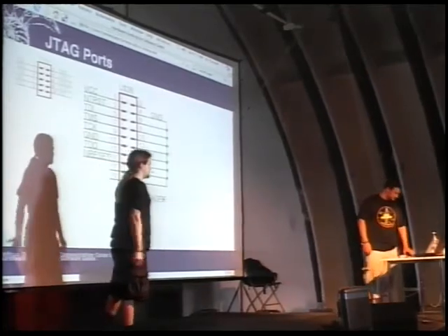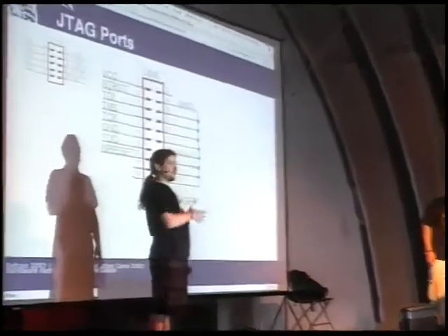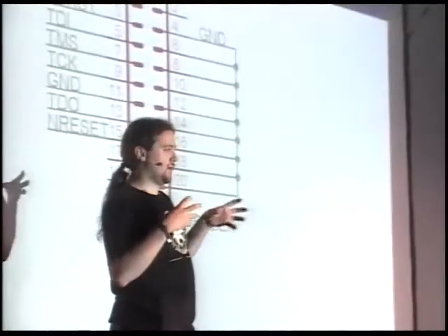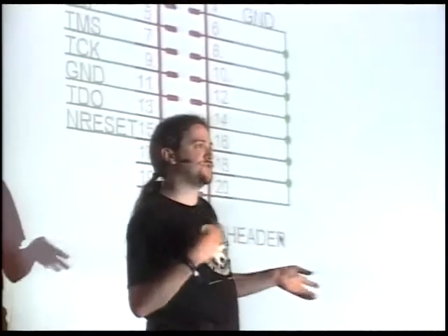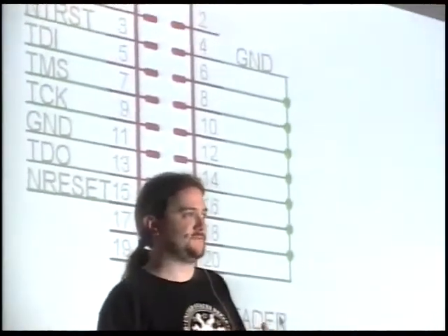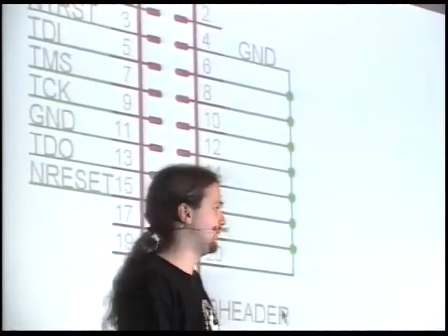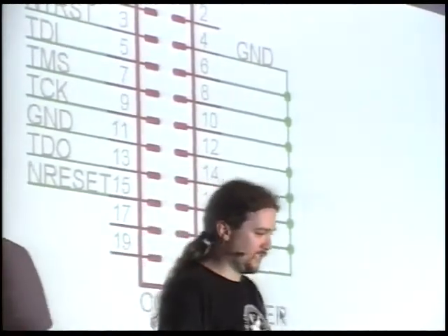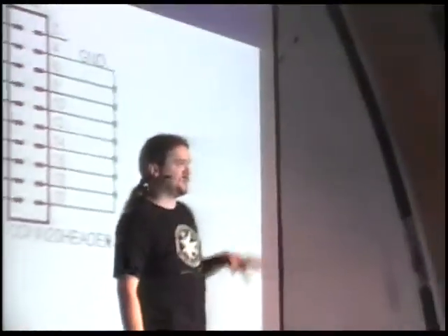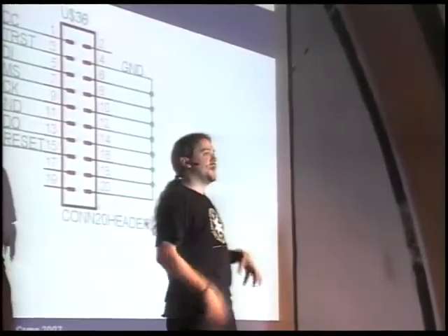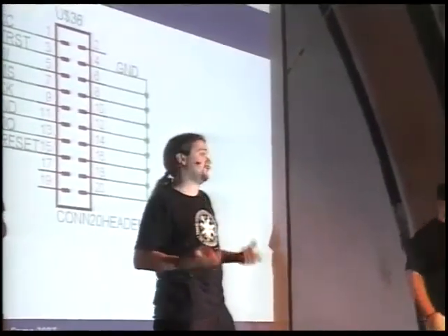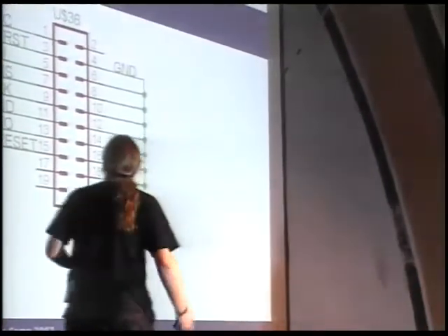Don't skip yet. While they're not standardized terribly well between manufacturers, usually one manufacturer will use the same JTAG pinout on all their boards. The router that we've been showing off and another router that I have both use MIPS processor cores, and their JTAG headers are both MIPS JTAG standard.